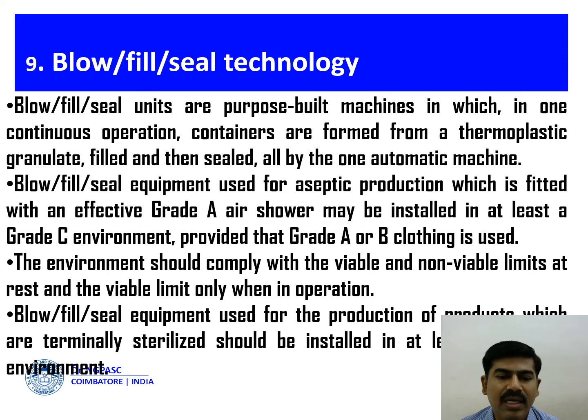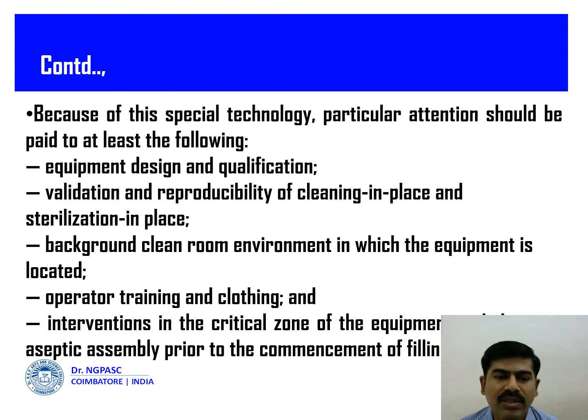Blow fill seal equipment used for aseptic production, which is fitted with an effective grade A air shower, may be installed in at least a grade C environment, provided that grade A or B clothing is used. So because of this special technology, particular attention should be paid to at least the following: equipment design and qualification, validation and reproducibility of cleaning in place and sterilization in place.